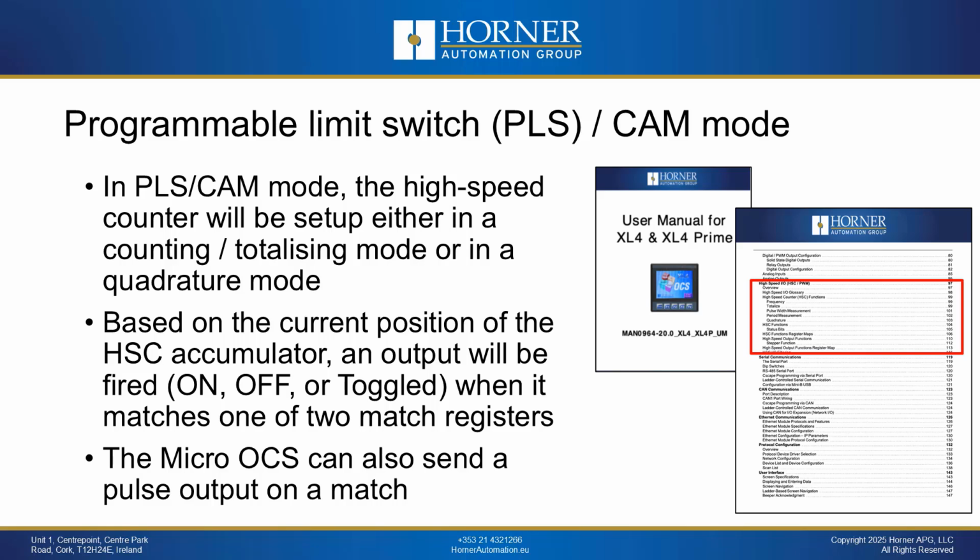Now when we say firing an output based on a high-speed counter accumulator, what it means is that you could be turning that output on, you could be turning that output off, or you could be toggling that output to the opposite state, when you have a match condition where the particular position that you want to fire that output matches the accumulator. So that is the key.